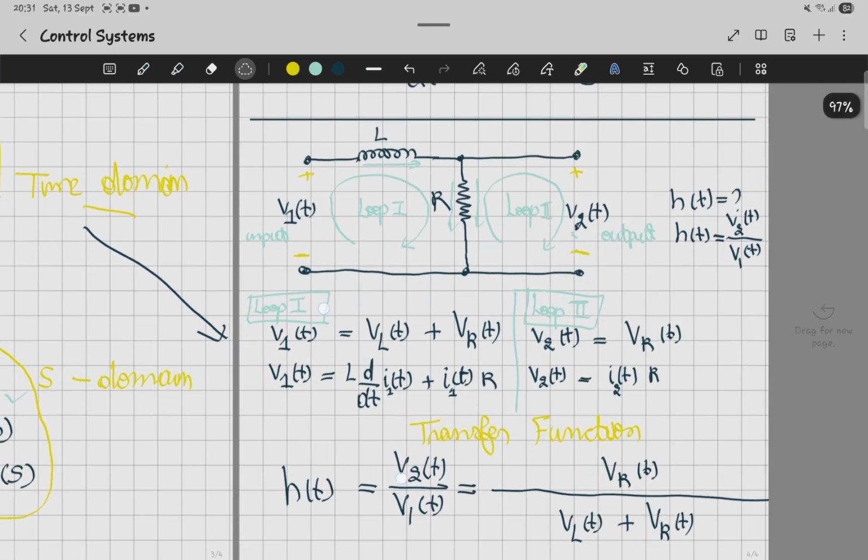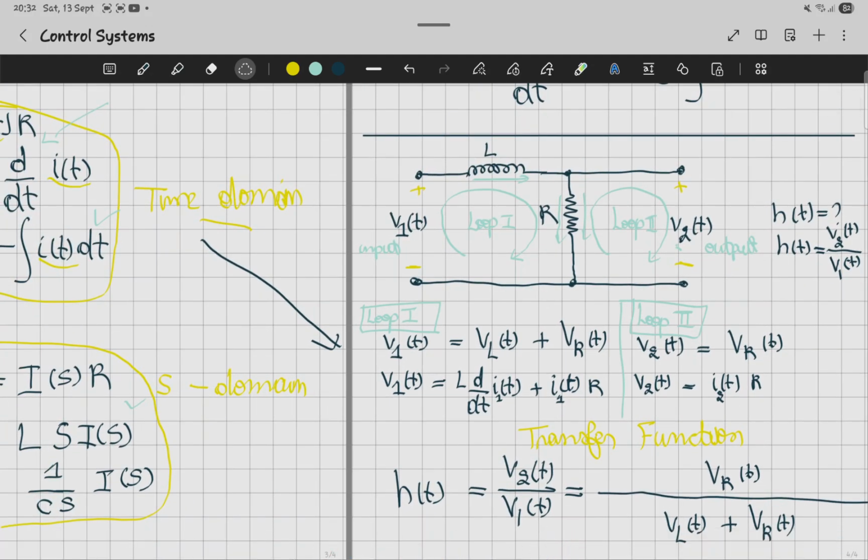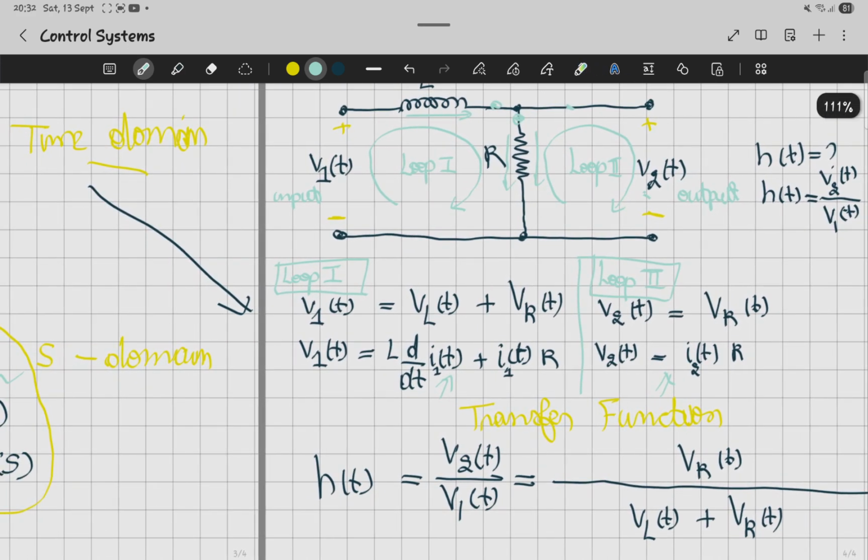So this is our transfer function, and if you want, you can go further and solve for it, or maybe we can use the formula that I just mentioned here. Also pay attention that you need to solve for the current, depending on the current that you get across the resistor, across the inductor, and in this line. Maybe we're going to see an example where we have defined the direction of the current and you can apply Kirchhoff's law. So this was just to give you an idea of how you can solve for the voltage in this type of equation.